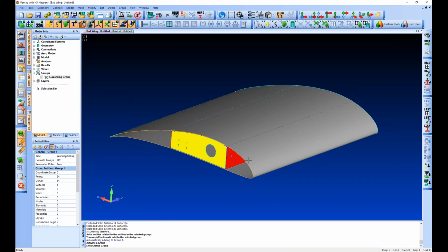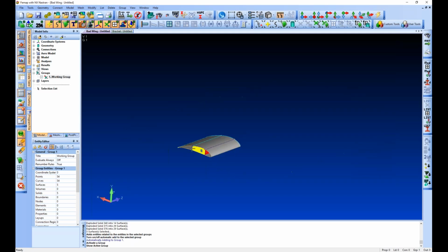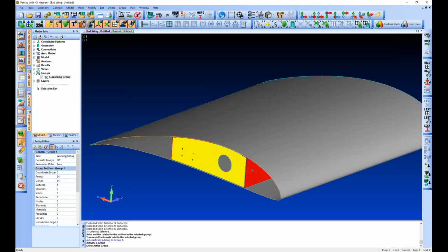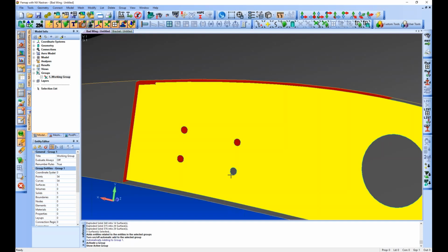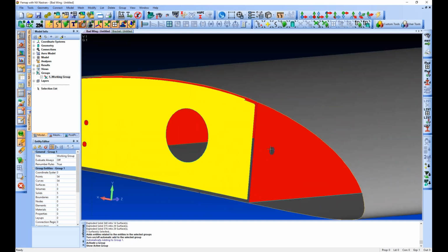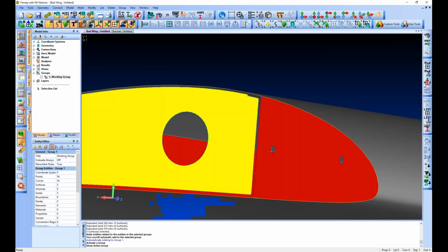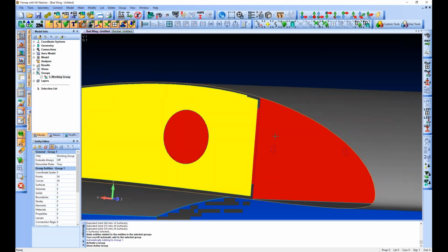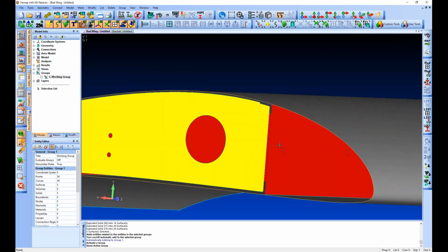First thing I think that makes sense for this model specifically is to just get rid of any unneeded features. So these bolt holes that look like maybe a servo mounts here, probably don't need those. This is pushing maybe. Maybe you might want to model this, but I'm not going to model this in this case. It's fairly small to the shear web. I don't think it's going to be an issue.